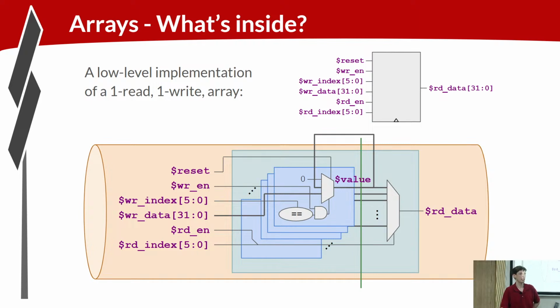If you're trying to read and write at the same time? Yeah, so there can be constraints based on the physical implementation of the register file that might not permit that operation. But logically, the way I've drawn it here at least, if you perform a write and simultaneously perform a read, you should get the value that you wrote. The write data comes through as the read enable is going through, and the data goes through this mux, through this flip-flop, gets selected, and reads out.